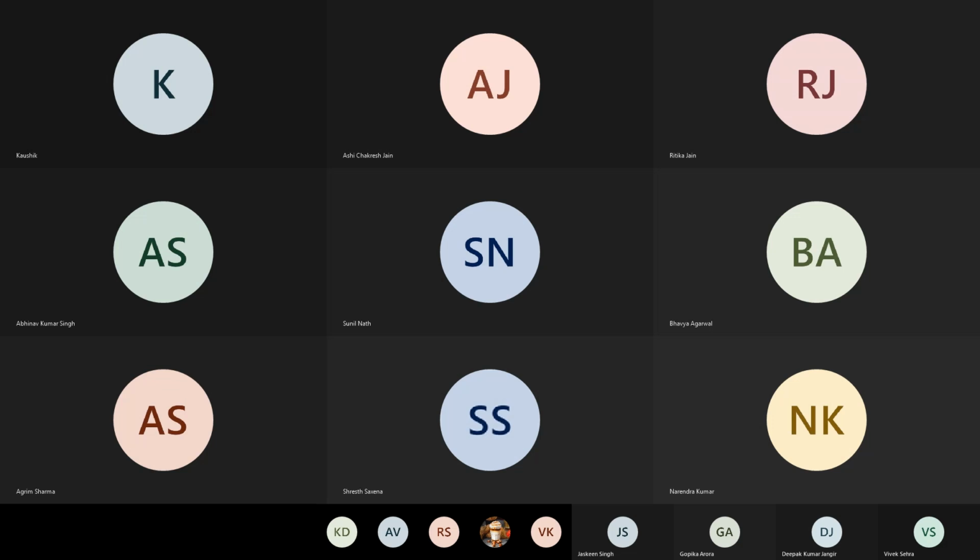So here you'll take the reactants at 533 Kelvin: 1 mole of CH4 and 2 moles of oxygen. Here we are taking complete combustion, so the mass balance is very simple, but since you know how to do incomplete combustion and limiting reactants, we can always have a problem where you have to do the mass balance.